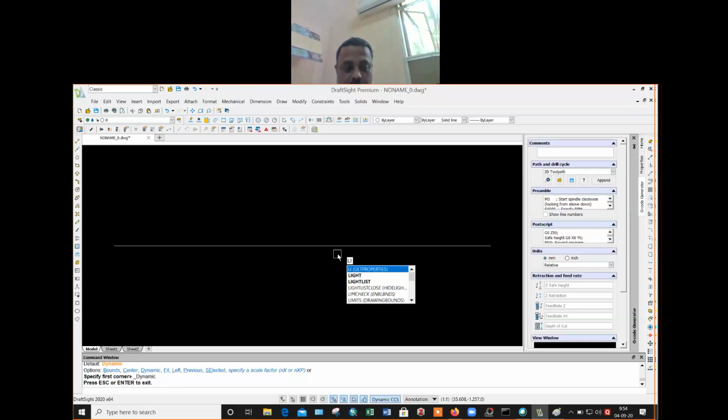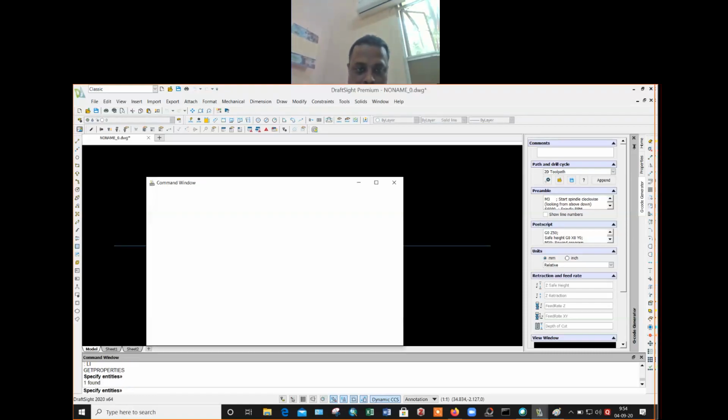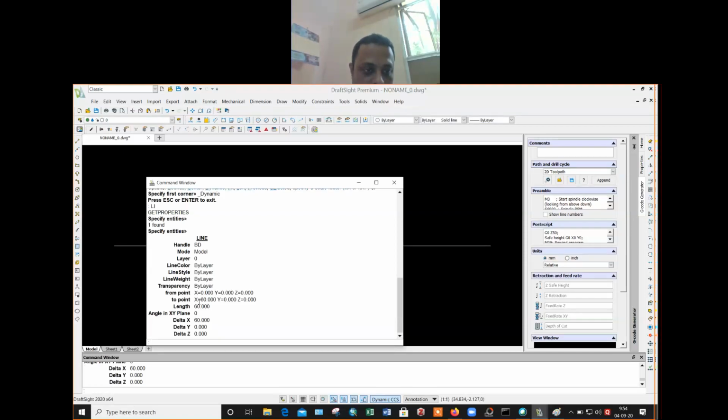Let me see the property of the line. How will I check the property of the line? By typing the list command, L-I-S-T, or I can type L-I. So on the screen I type LI, list, then click on the line and enter. It says delta X is 60.